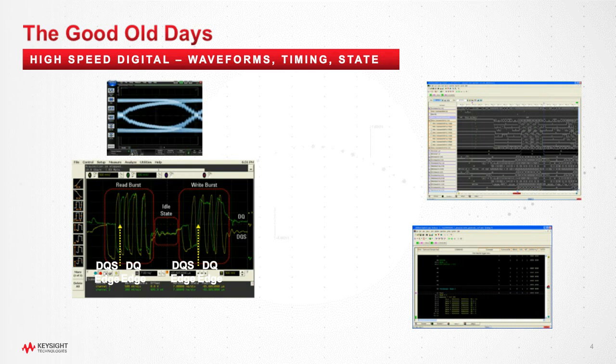And so in the lower left here, here's an example of, say, the relationship between data strobe and a data line, and the spec would be describing what the setup and hold time is of that strobe of the data line, DQ, compared to the data. Other ways that you would visualize and characterize and debug designs is with timing and state analysis.